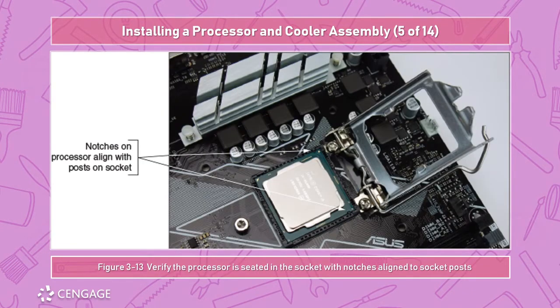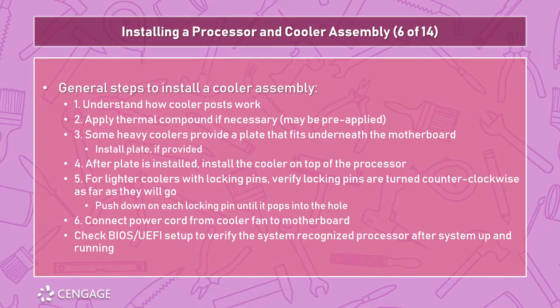Here we see those marks a little bit more clearly. You can see on the corner of each side of the processor, top right, bottom left, there are little circles, whereas in the top left, you see there is a triangle kind of pointing. And then you have the little notches that allow you to indicate which way the processor should face.